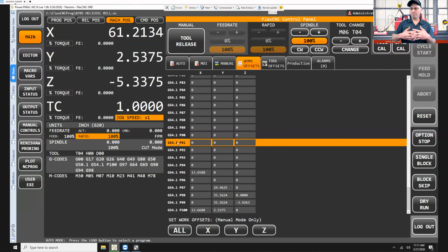And once you have the pocket on the table, you have it all set up, when you tell it to do a tool change from the tool in the carousel to one of these outside pockets, it'll drop the carousel tool in the carousel, then go all the way up and travel over to the external pocket and come down and pick it up.